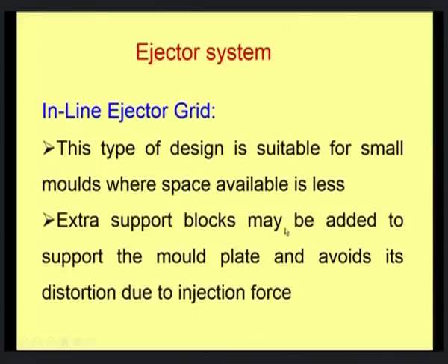Extra support blocks may be added to support the mold plate, because the mold plate has to be strengthened sufficiently so that it does not get distorted due to the high injection force, because the resin is injected at a high pressure from the nozzle to the mold. Therefore, this mold plate should not get distorted, in the sense its position should not be altered.